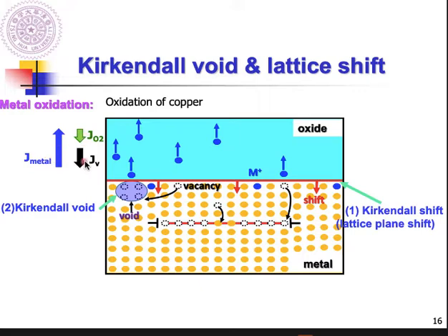And so in order to get the net flux equal to 0, that will lead the vacancy flux downward, toward the bottom. So this is also the Kirkendall effect. For the criteria of the Kirkendall effect, the first one is that you have two different compounds, and there's a concentration variation along these materials. Yes, there's dissimilar flux, and we got the vacancy flux here.